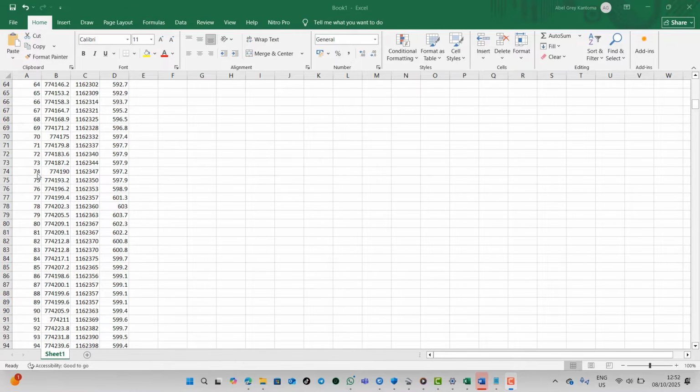If you look at this now, like I said earlier, this is our point, this is our easting, this is our northing, this is our elevation. Similarly, if this was to be here and this easting value to be here, it will now be point, northing, easting, and then elevation, right? By the time we open our Civil 3D software, I'll be able to explain that better for you to understand. I have spoken extensively on this. I wouldn't want to go too far anymore.